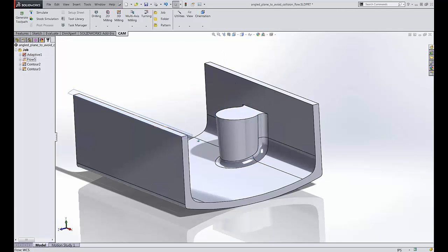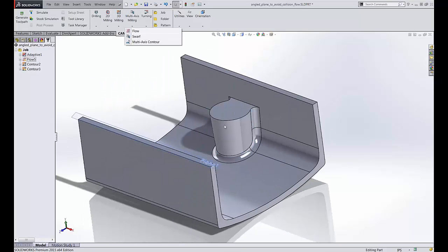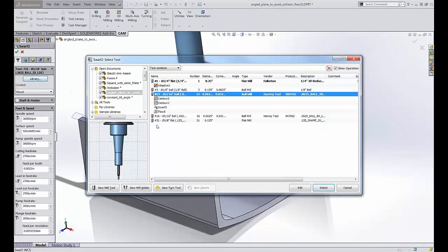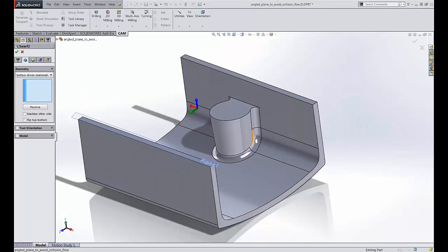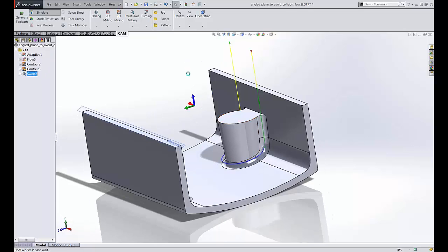Oh, and I should also say this is actually a great candidate for a swarf machining operation normally, because it is a planar or a conical surface, so it does have an axis that can be aligned to a straight tool. We'll actually generate one here real quick. I think I have a tool. And we'll see maybe some of the problems with why you maybe wouldn't.